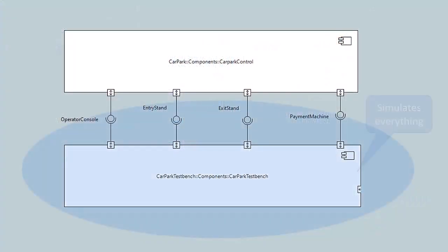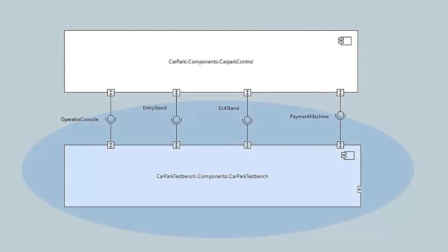For example, when you're running your models under test in Verifier or using generated code on your development host, the test bench needs to simulate everything in the system that cannot easily be connected to Verifier or the host executable. Running in the target deployment environment presents a number of interesting challenges and some opportunities. We typically recommend a phased approach for this type of testing. So start with a test bench that simulates everything that your models need to interact with.